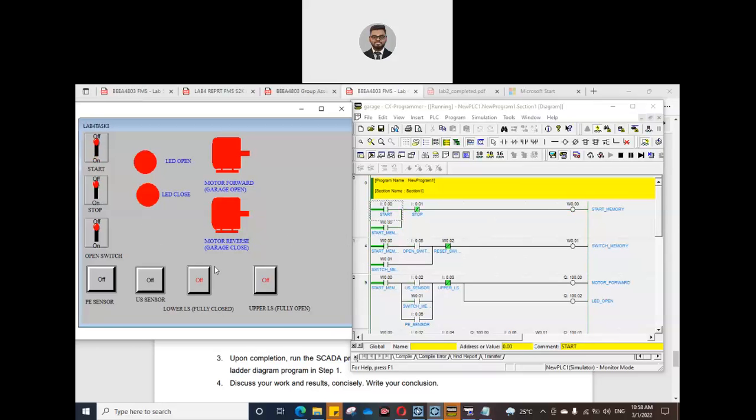So let's say the garage door is actually open, and you press the start button. Here it shows the motor is closing. But if it is in the initial condition, closed, the lower limit switch will be triggered. If it hits the lower limit switch, the motor stops. So now we can see that if it is fully closed, when you press the start button the motor is not reversing. It has already stopped because the lower limit switch has been hit.